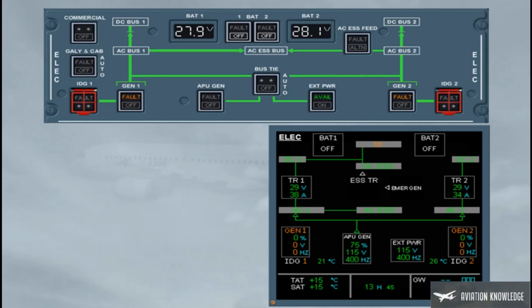As soon as the related battery push-button switch is set back to on, the related BCL connects the battery. A battery is correctly loaded when its current drops below 60 amperes after 10 seconds and continues to decrease. If not, you must wait until the charging cycle is completed and perform this check again. Note, the charging cycle is completed when the BCL has disconnected the battery.